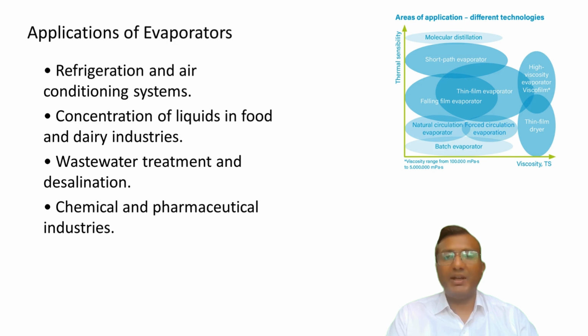In chemical and pharmaceutical industries, evaporators concentrate solutions or purify compounds, handling high viscosity or heat-sensitive materials via forced or falling film designs. Molecular distillation, a specialized evaporation process, is used for high viscosity substances in pharmaceuticals.